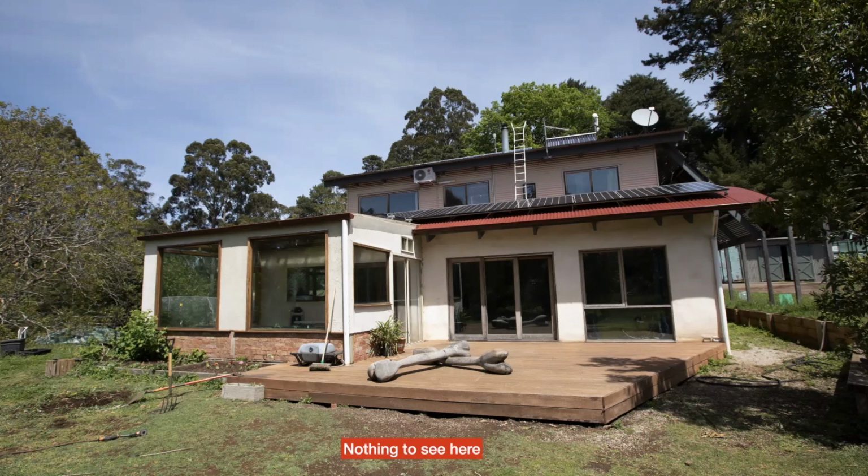Okay. Ruth asks, does it have to be resting on the ground? Perhaps strap it above the bathroom window on south wall? Another gotcha. Battery system needs to be under 2 meters. So the top of the battery system can't be above 2 meters. So that would kind of limit you how high you could put it up the wall.